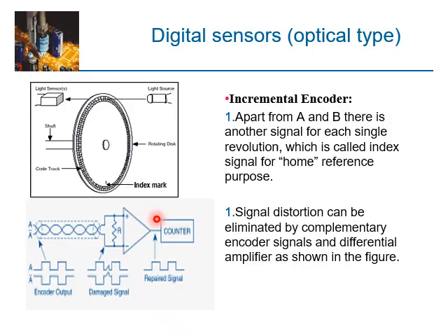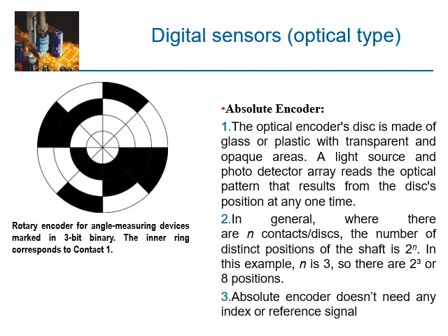So usually you will have a total of 6 signal channels for an incremental encoder. This is called an incremental encoder. There are two types of encoder: one is incremental, another one is absolute encoder. In an incremental encoder, you will have 6 channels. Now let's come to the absolute encoder. In an absolute encoder, you do not need to do homing. Rather, you have many disks, not just 2 disks. You have 3, 4, 5 disks. This example shows 3 disks. Here, these disks are coded as binary.